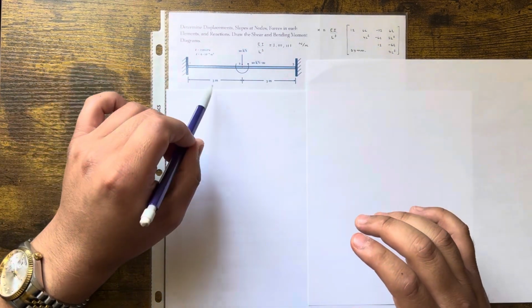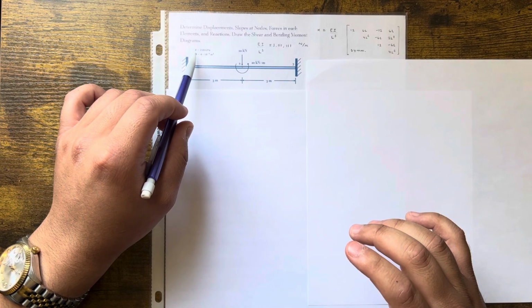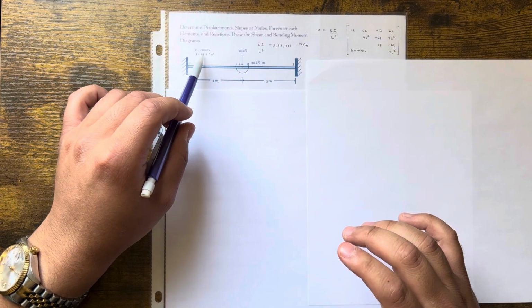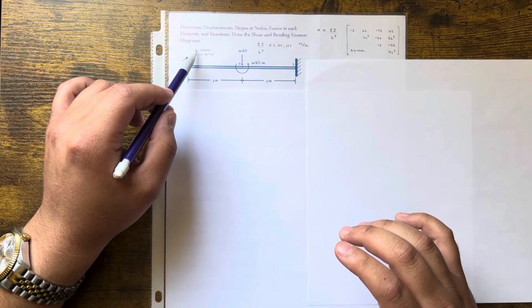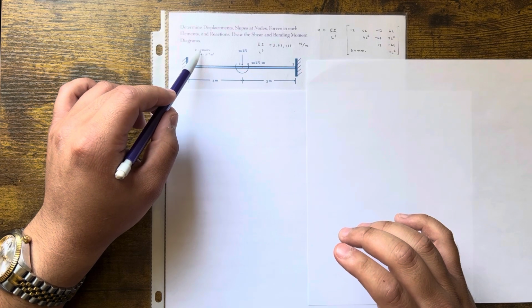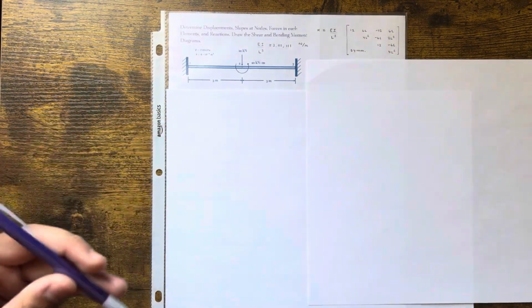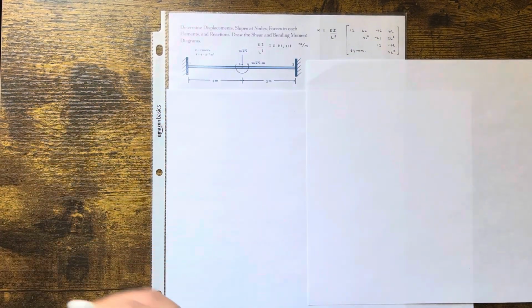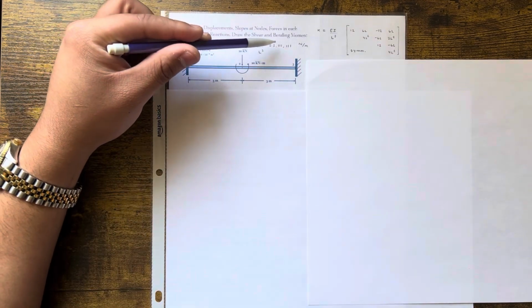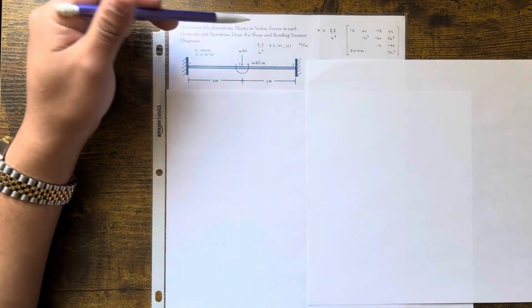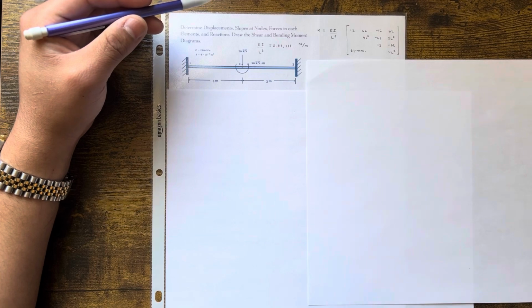So in this case, since they're the same length, they have the same moment of inertia, which is 4 times 10 to the negative 4. And then they also have the same modulus of elasticity as steel, right? 210 gigapascals. So for both members, our EI over L cubed is going to be 3,100,000, this number that you see right here, okay? Newtons per meter. That's a stiffness value, okay?